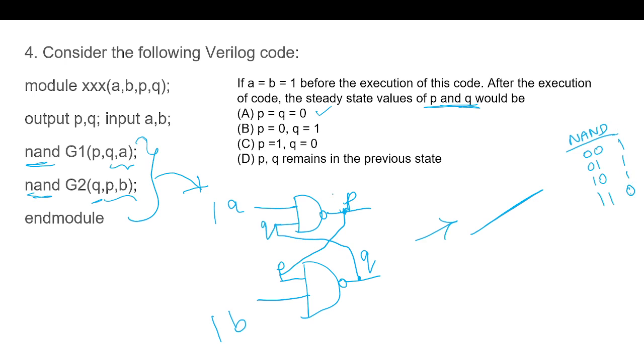So which type of circuit is it? Sequential, right? Latch. Yes, it is sequential. Name of the circuit? NAND latch. Yes, so it is an S bar R bar latch. In that circuit, if any one of the inputs is 1, whatever the other input is, it can either be 0 or 1 based on the other input. So I will be able to retain the previous state.